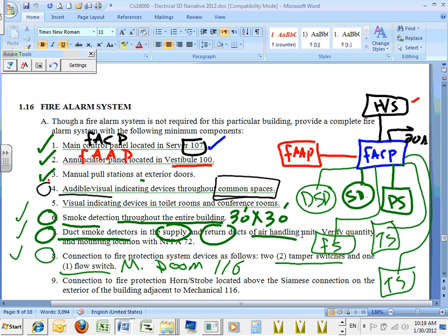Is the strobe simply alerting, not necessarily directional? Here we put them over the door, I assume. To alert. Yeah, the strobe is supposed to alert you to the presence of the fire, not the direction of flow. The direction of flow, if this is a public area, you should see where the fire escape route is, and there will be a fire escape route. Now it doesn't mean you can't use it to indicate the exit of the room. You can, but the way I understand it, for all practical reasons, you could have put that one right there. Okay, everybody knows how to use this.